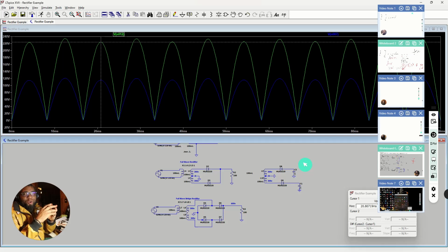has designed things in a certain way to make them amenable for different projects. But because of that, you're going to find that there are some things you won't find straight out, like certain voltages of transformers, and you'll have to know stuff like this to understand how to actually achieve what you want. Let's say I wanted a 6-volt output and I can only find 12-volt transformers. How do I get 6 volts? What if I want 6 volts but at like 10 amps? That means I have to use a huge resistor. Sometimes it'd be impossible really, and you'd just be wasting energy.